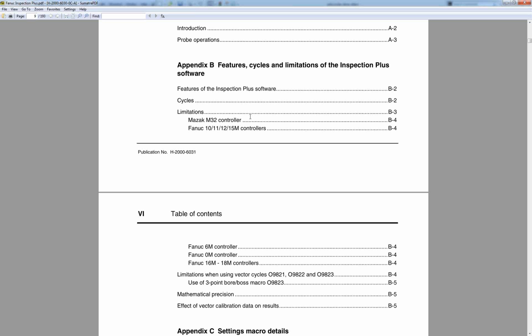You have Renishaw cycles, okay, talk to your reseller in your area, maybe you can buy it, and give the customer this package of cycles for which you already have the post. If you cannot do this, you have to write this include file or the entire post, whatever, to support the customer's cycles.